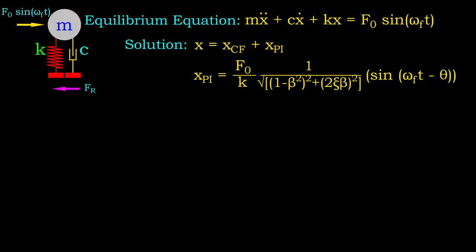We have solved for the response of a damped SDOF system when it is subjected to an external force. This scenario is known as the forced vibration of a damped system, and its dynamic response can be further categorized into transient and steady-state responses. We know how the structure would react, but how about the reaction force at the bottom of the dynamic system?